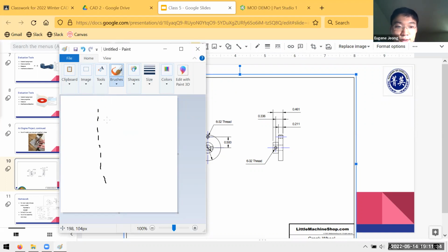You also could do a different approach where you have your axis of revolution there, and then you have an L-shaped piece. You can imagine when you sweep this 360 degrees, what you end up with is a hole in the middle, your first wheel, and then your big wheel on the outside.